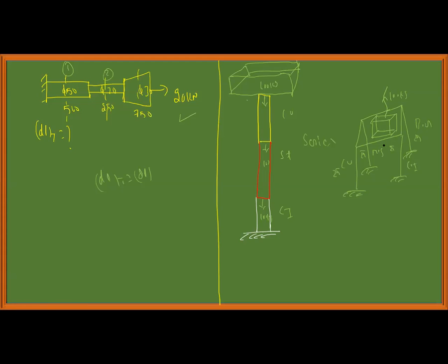In this arrangement, the total load is equal to the load on each section, copper, cast iron, mild steel, plus brass, plus aluminum. So total load is the sum of all these loads, but the deformation remains the same.